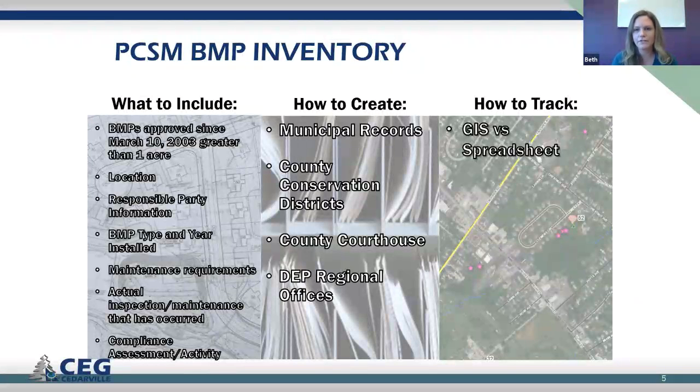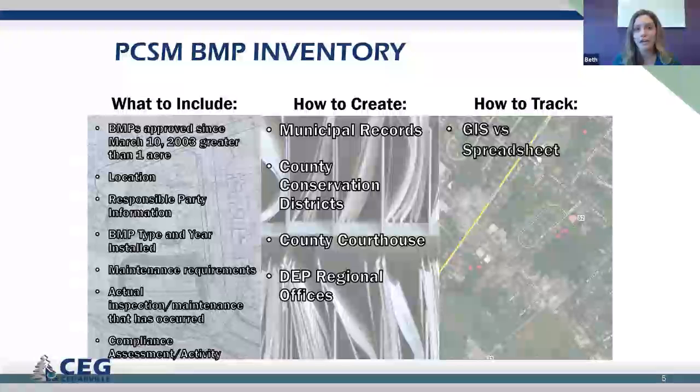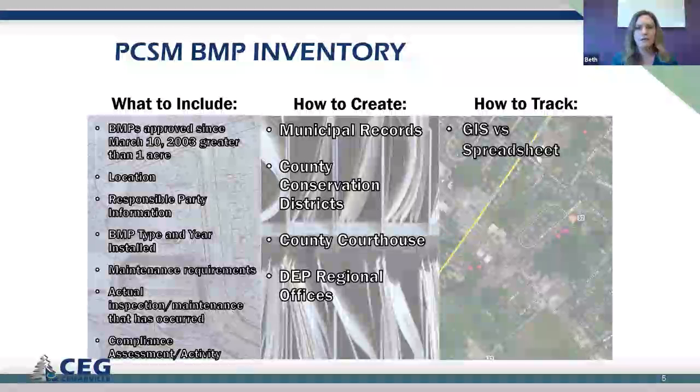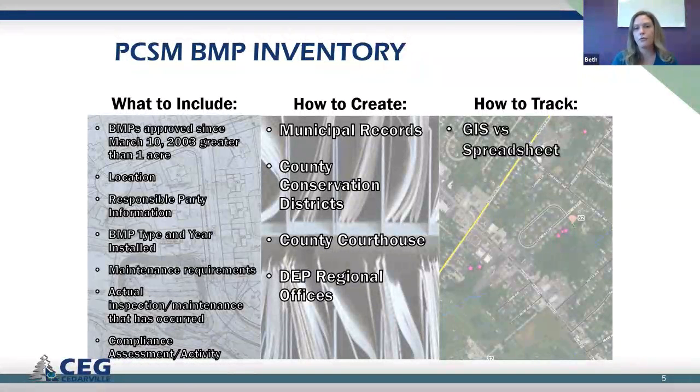But you need those plans in order to know exactly where that BMP is to conduct the inspection, and also to check for any O&M requirements, to check the details of how that BMP was supposed to be constructed. And how to track: GIS versus a spreadsheet.